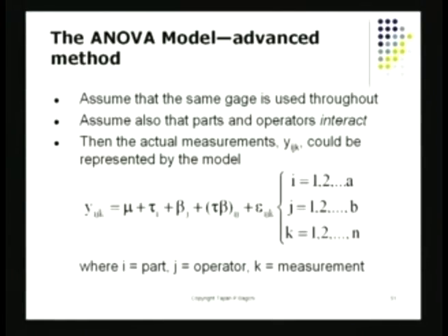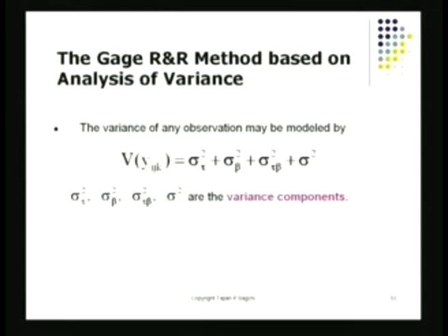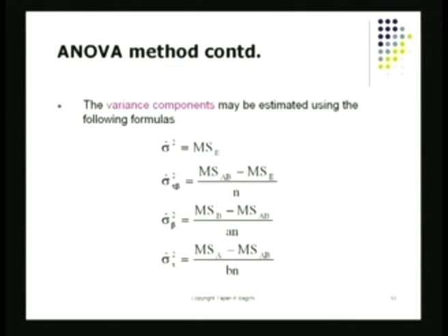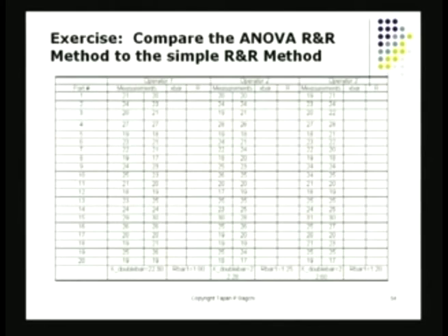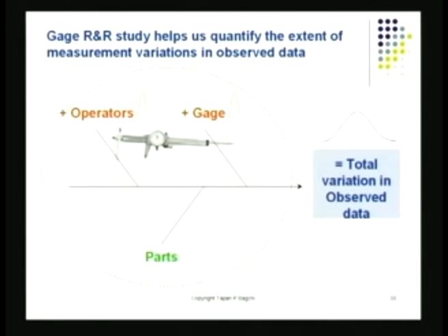And of course, there are fancy methods called ANOVA. Those can also be applied, and they can also be used to do measurement system analysis. The ultimate idea, of course, is that you have to make sure that the measurement system, whatever gauges you are using plus the procedures they are using, do not contribute much. And what you observe is exactly what the true variation is. So therefore, you can rely on the data that you produce, because your decisions have to be data driven.